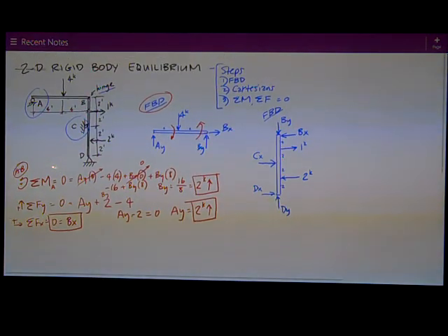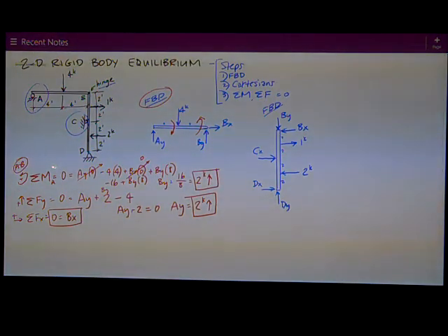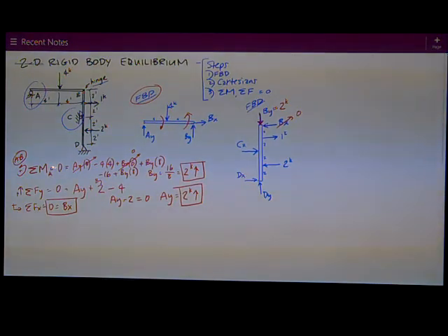So now I've got AY and BY. My signs assumed on the free body diagram for AB are correct, so I want to put those numbers, or at least for BY. If it was up on AB, it's down on BCD, so it's 2 kips down correctly. BX went to 0. So now do the same thing for BCD.